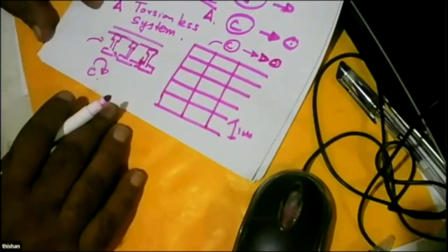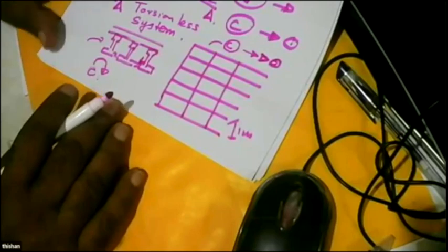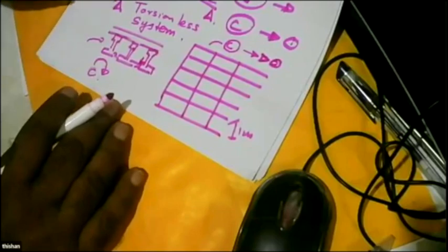But what will happen? Because you have made the torsion close to 0, you get a higher bending moment. So we'll be designing these beams for higher bending moment. So in the compatibility torsion situation, there's no risk of collapsing. There's no risk of cracking, even if we ignore torsion.